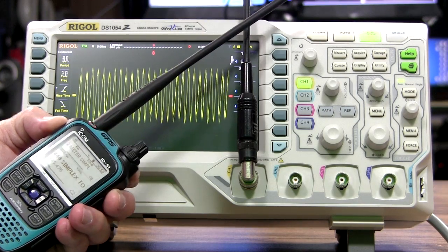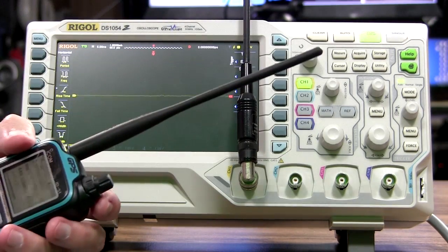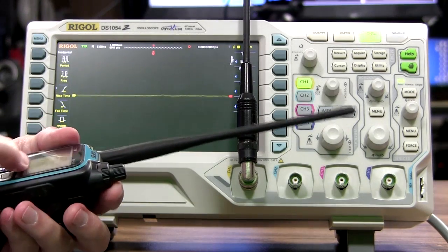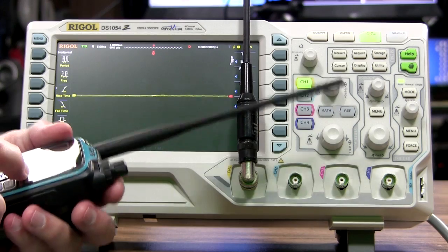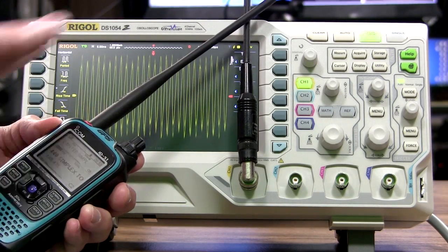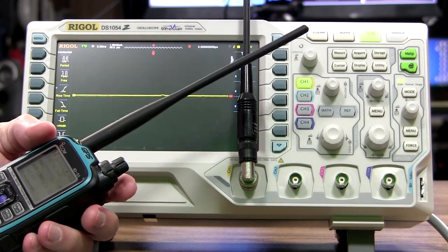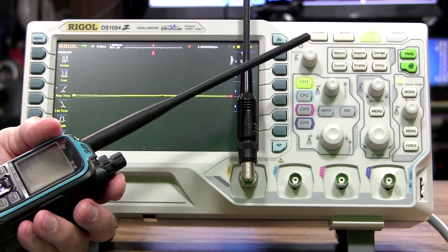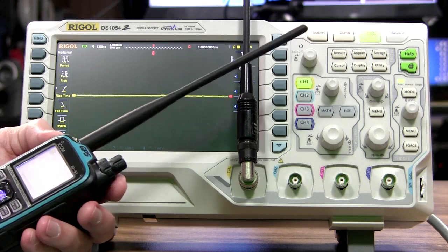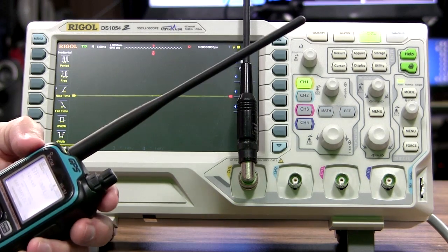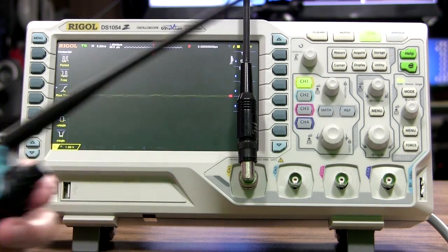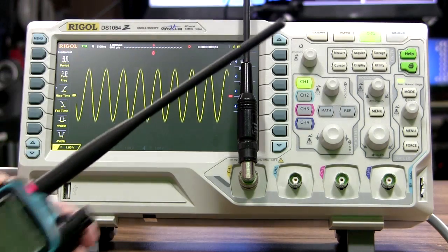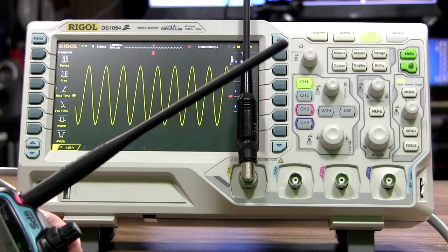The reason for that is this scope is limited to 100 megahertz, which is a good scope. But we're trying to look at 440 megahertz with it, so it's out of band. So you're basically overloading it, but you're getting a little bit in it. 2 megahertz, I mean 2 meters, was the same way. It's out of band as well. It is, but it can still measure it. And if you notice, when I get real close to it, it goes to clipping. That's just because we're overloading it.